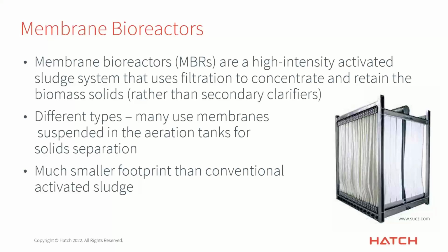They do have an extra cost, though, of course, in terms of the energy required to draw the permeate out of the system. And they do have some other operational considerations that you have to take into account. They have to be cleaned and backwashed and keep the solids and, you know, just general maintenance to keep the membrane surface in good shape.